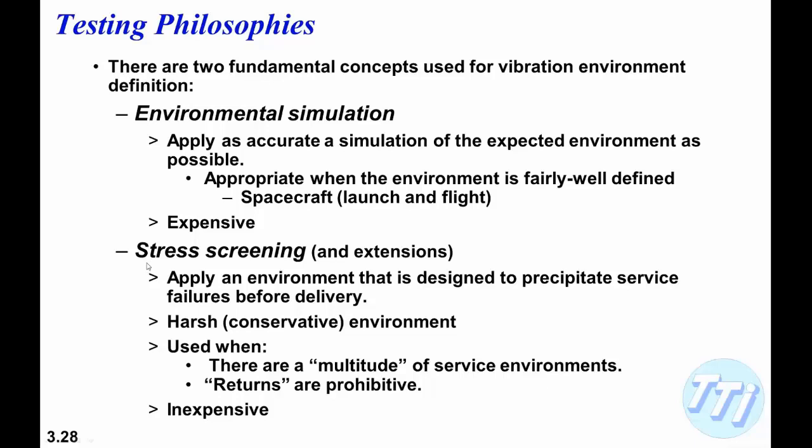The other possibility that has become popular over the last 30 or 40 years is stress screening and extensions of that. This is to apply an environment that is designed to precipitate service failures before delivery. So it's a harsh, conservative environment. It's used when there's a multitude of service environments and returns are prohibitive, as in the computer business. And here, this is failure stimulation as contrasted to failure simulation.